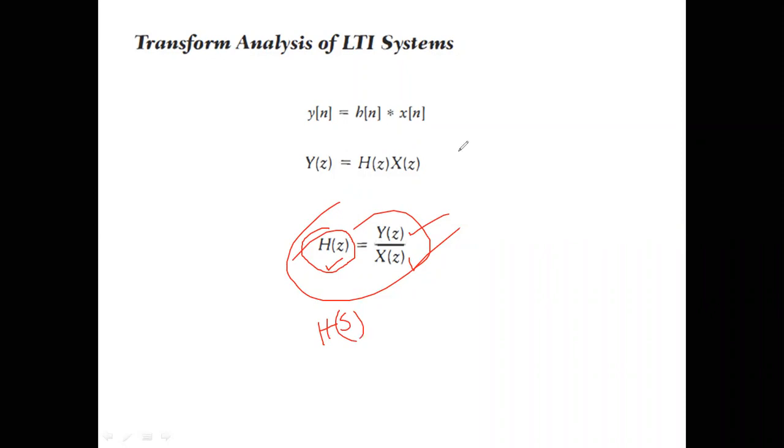Now let us see. Are we clear here? What is a transfer function? If you take the Z transform of this entire equation, you get the ratio. The ratio of the output divided by input is the transfer function, and if you take the inverse of it, you can always get the impulse response. It is a handy tool, because deconvolution, the so-called very complicated iterative process, is converted into simple division.